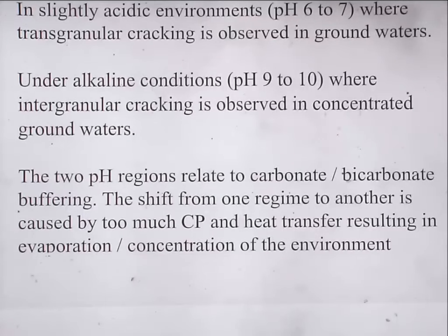if the corrosion is too fast, you just passivate the whole thing so quickly that it never gets a chance to grow. If the stress is too high, you end up with a brittle fracture rather than a crack, because the corrosion doesn't get time to occur. So there's a balance between a number of factors, and people tend to think, oh, right, it's stress corrosion, therefore you should use a corrosive environment. And I used that word earlier on, and I corrected myself.